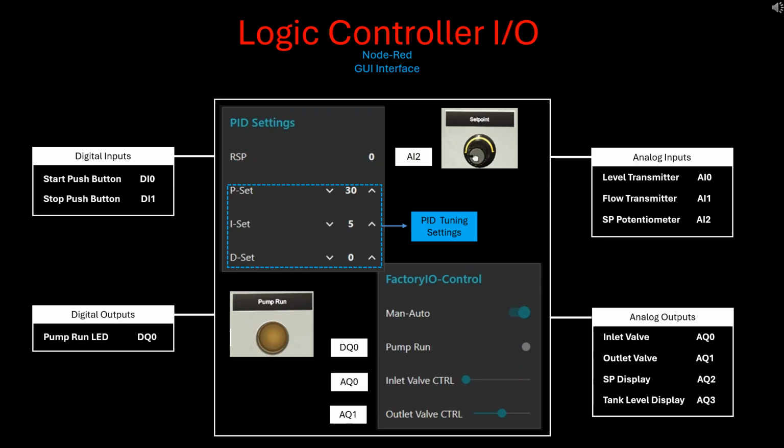A customized built-in proportional integral derivative, or PID, controller is utilized to control and manage the tank level to the desired value. The PID loop uses the level transmitter as the input, while the input flow control valve is the output. The set point determines the tank level target value for the PID algorithm, which must compensate for changes in load demand. The load demand in turn is manually changed via the outlet control valve.